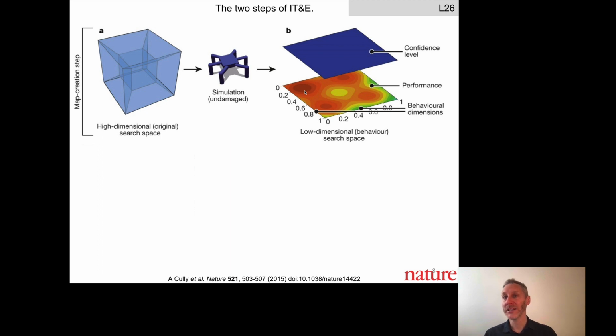So how does MAP Elites work? MAP Elites is actually a relatively simple evolutionary algorithm. We generate a bunch of random controllers from our high dimensional space. We create random neural network controllers, run each of them on the hexapod, figure out where those results should be stored in behavioral space, and drop the fitness values into those pixels. And if there's a collision, we keep the best one.